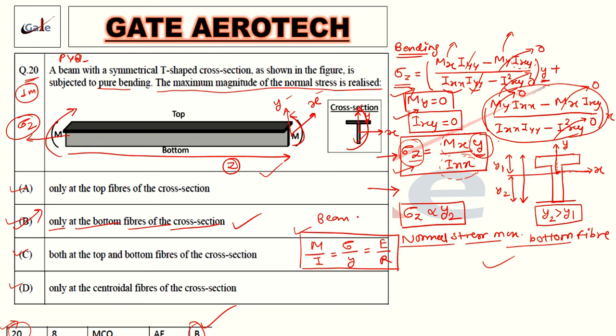We many times say the simplified beam equation. So according to this, you can also write it this way. Taking these two components, stress will be M by I into y, and when Mx is only acting, this becomes Ixx, and this becomes sigma z.